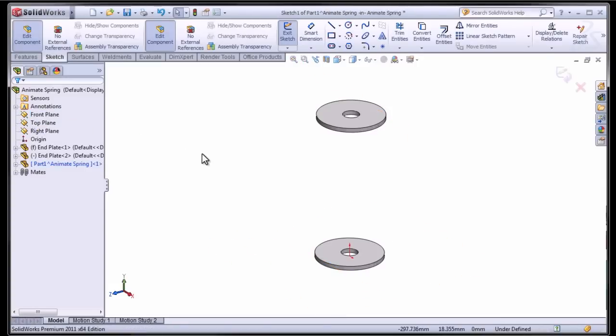And I'm going to create that starting with a sketch on the front plane. So what I'm going to do is create a sweep. So along what path am I going to create my sweep? Just like any other time, that's what I have to do: 2 sketches, a path, and a profile. This time I'm going to use it a little differently, but that's what I'm going to start with.